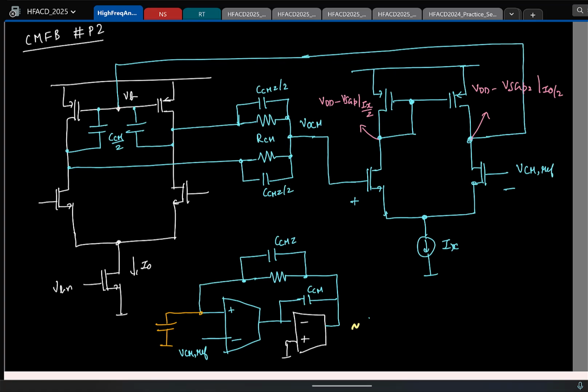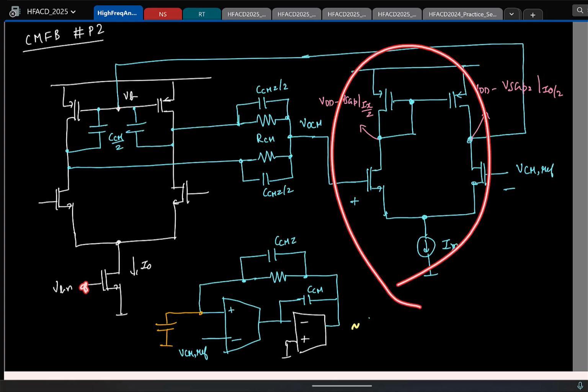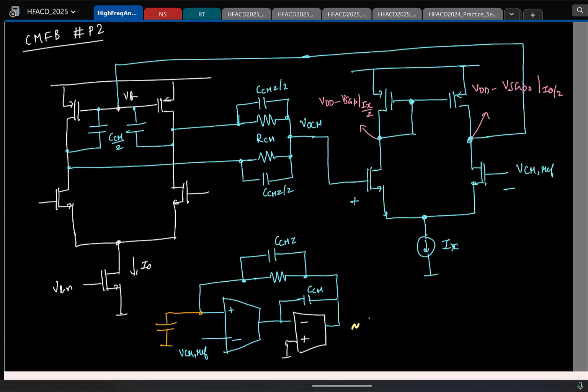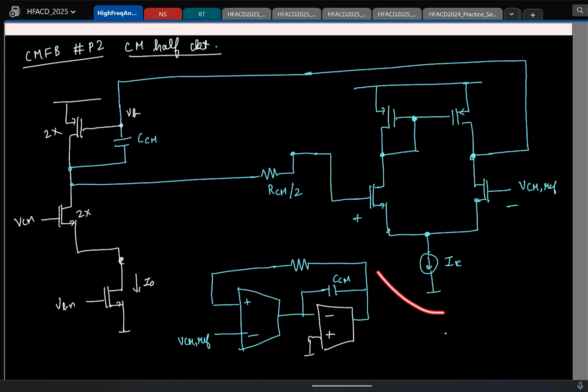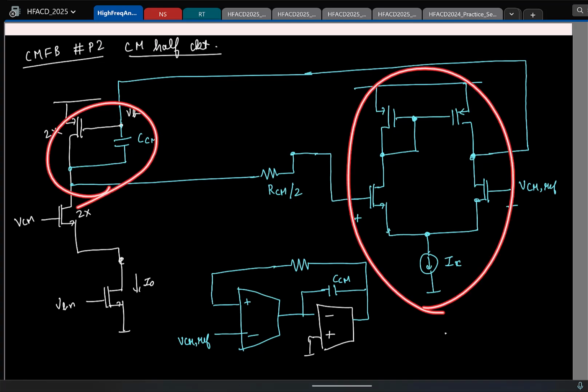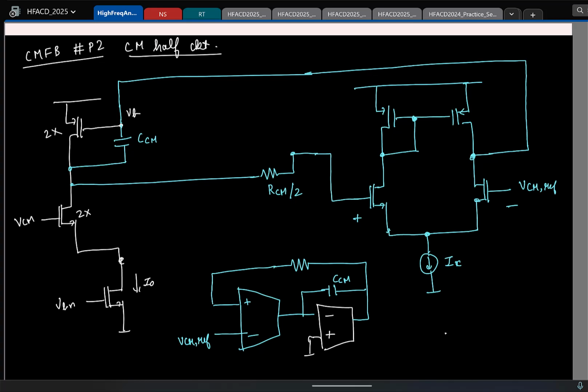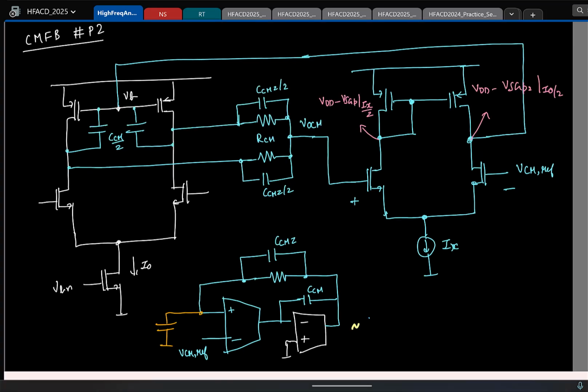On the contrary, if I went and tuned the NMOS current source's bias voltage, then you will find that using a PMOS input pair is better. The same considerations you will have while designing a two-stage OTA, right? If your first stage is NMOS, you saw a PMOS second stage is better. Similarly, if this connects to an NMOS second stage, then having a PMOS input as the first stage is better. Okay. So then one other point to take care is this.